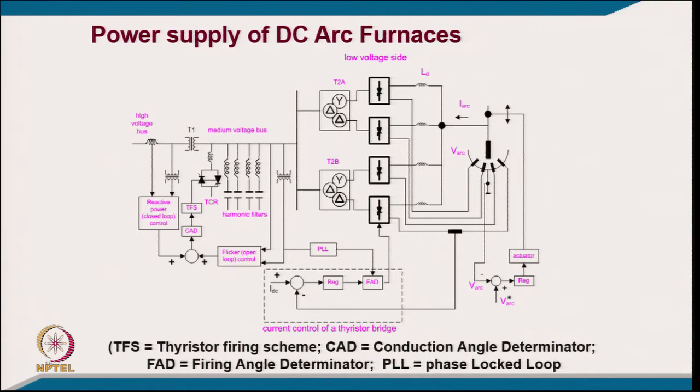So, if you look here, we have a typical example of the converter with transformer isolation, a 24 pulse converter, and this is controlled because even with the 24 pulse converter we are using thyristors, it requires reactive power as well as harmonics are also there. So, for that we normally use a passive filter.